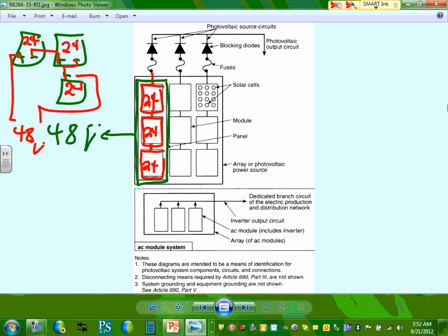You guys got the solar photovoltaic system. You can keep ramping these up to about 600 volt. Now, some cells are 24 volt, others are different voltages, depending on the voltages. I'm just using a 24 volt. So if you have 10 of them, 10 times 24, they'll give you 240. 20 of them, 480. So to get 600, can you guys divide 600 by 24 and tell me how many modules roughly I need? 600 volt by 24.